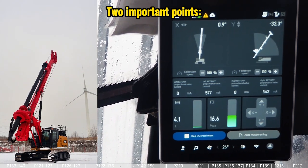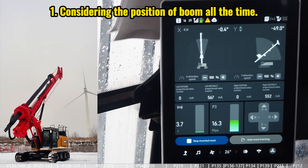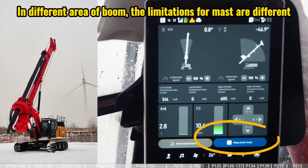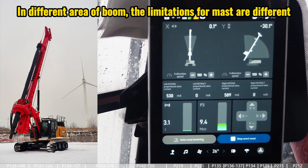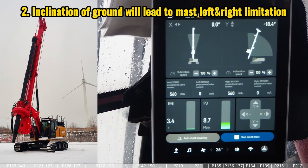But there are 2 points that need to be mentioned here. The first one is we need to take care of the position of the boom all the time if you want to have a movement for the mast, because considering the different position of the boom, the limitation for the degree of the mast open and close is different. And the second point is we need to take care of the inclination of the ground.